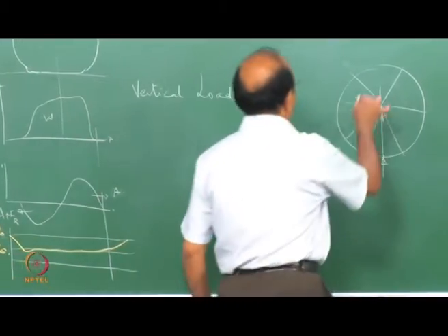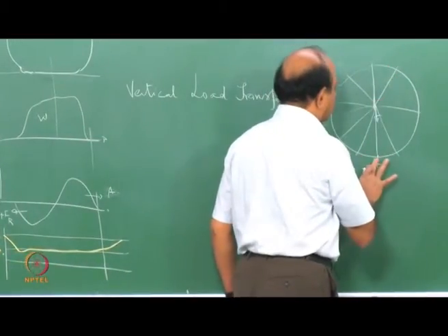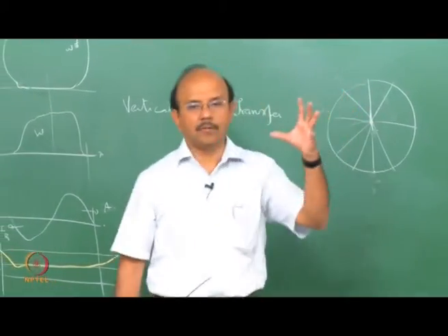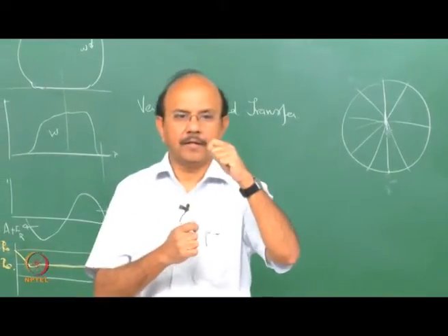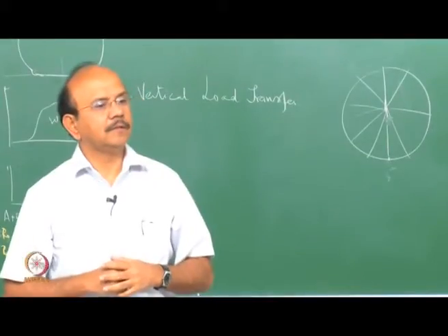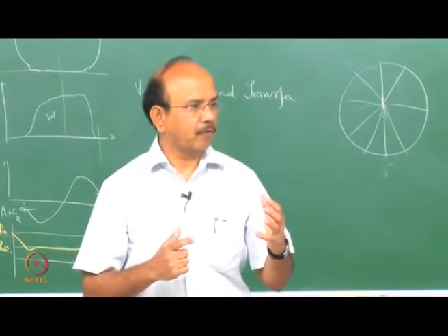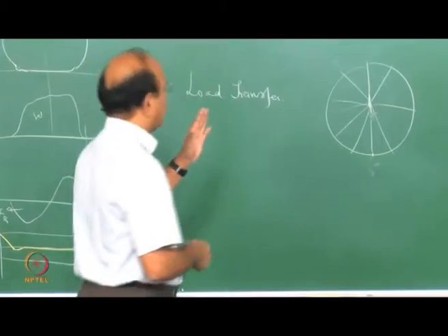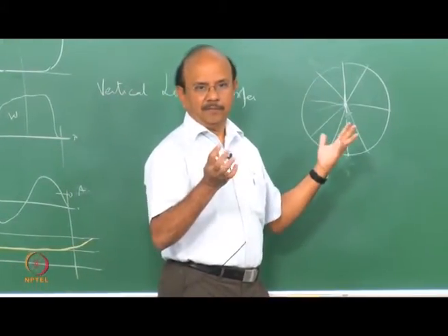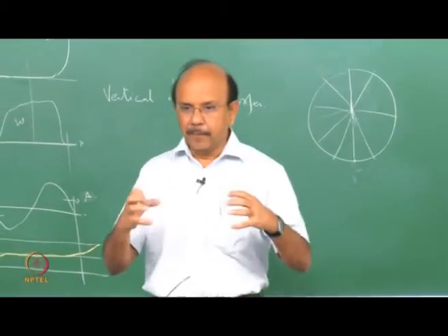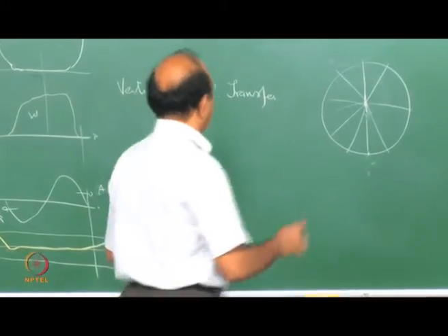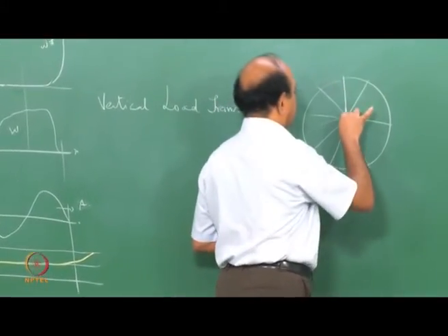Right. So let's say that the wheel is not on the ground, just take the wheel out. Then there's a tension in the spokes which are opposite to each other, and they would cancel each other. So it's not that the wheel will run away in one direction or the other. They are under equilibrium because of the forces that are inbuilt into these spokes. Clear?